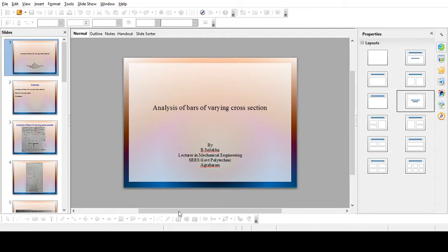Now, how can you find load? Stress is equal to load by area. So load is equal to stress into area. Maximum stress 50 into area is 100 pi. So 100 pi we got. So 100 pi into 50 is 15.7 kilonewtons. Okay. Next, total elongation in length.